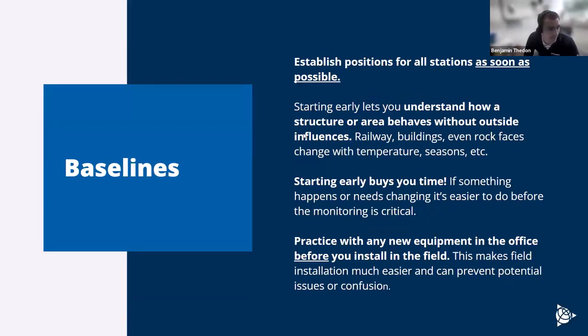So the baseline. I know it's very easy to say, but you need to start your baseline as soon as possible before the project starts, in order to analyze the environment and make sure the displacement you're going to have is not due to natural movement from temperature, wind, or other factors. Start early to understand how the structure or area behaves without outside influence. This structure can be a building, railway, or rock face, so it's very important to understand your structure before you start monitoring.